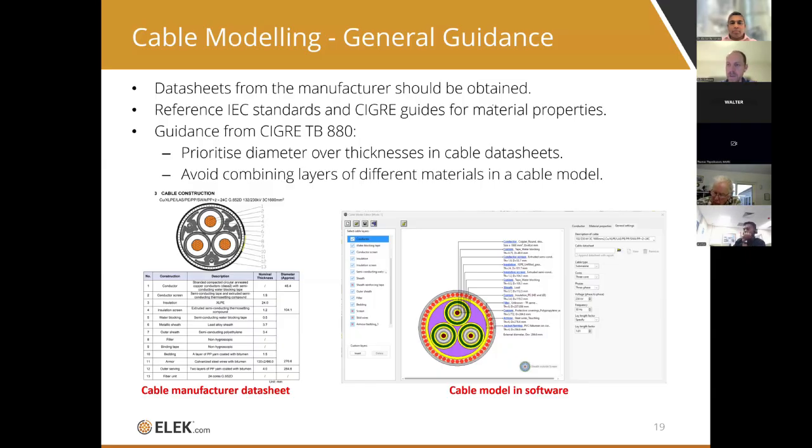What else, Edson? Lay length. Lay length of wires, yes. The overlap of wires and tapes. And all the material properties, like thermal resistance, are very important for all the layers. It makes a big difference, what you assume.